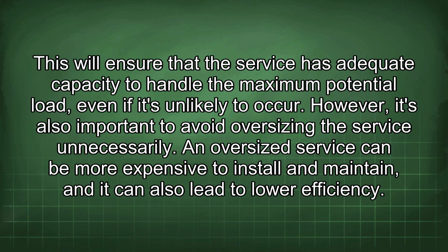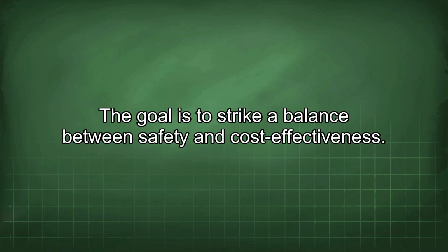This will ensure that the service has adequate capacity to handle the maximum potential load, even if it's unlikely to occur. However, it's also important to avoid oversizing the service unnecessarily. An oversized service can be more expensive to install and maintain, and it can also lead to lower efficiency. The goal is to strike a balance between safety and cost-effectiveness.